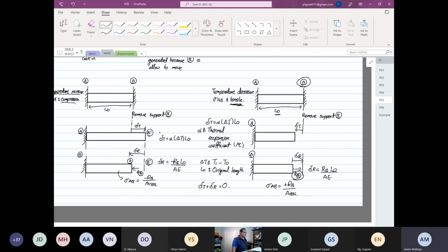We're talking growth, expansion in the axial direction. What about the radial? Isn't there implications too for temperature? So usually when temperature increases, there's an expansion, right? Like the situation on the left. When I remove the support at B, it grows. But in reality, B is down there restricting it. So to restrict it, you have to push it back.